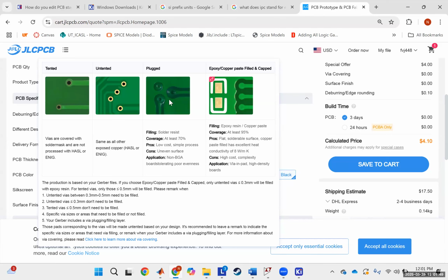If you have these pads that are really close together, solder may try and wick from your pad to your via while you're soldering. If you're not super careful or just not super experienced at soldering, that can happen, and then you can cause a short circuit, which would be pretty bad for your board. You'd have to get some solder wick to get the solder off, or find some other method, or maybe move and use one of the other boards they sent you if the situation's really too bad.